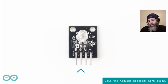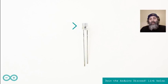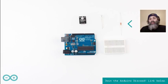LED itself. And then we have the photodiode, and the photodiode has that tiny capsule up there. It looks like a tiny LED, but it's not. And that tiny capsule up there is the one that contains the light detection system, and it has to be controlled with or polarized by using a resistor. And in this case, we're using a 220 ohms resistor, if I'm not mistaken.